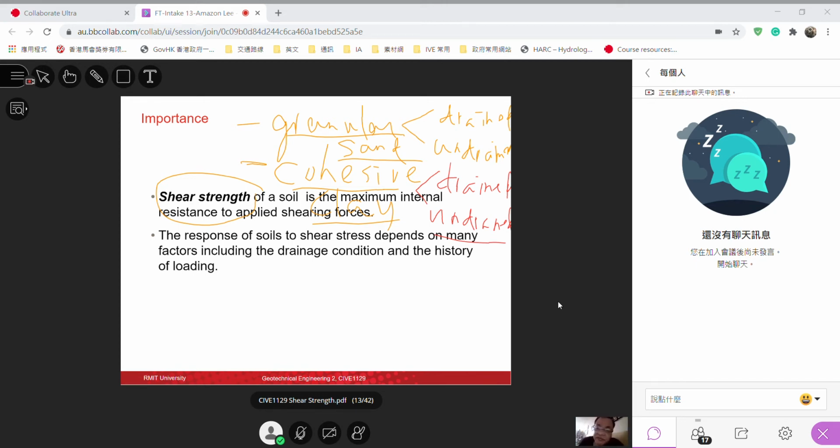Now, as I mentioned before, a lot of students are quite afraid of geotechnical engineering and soil mechanics, because in concrete, if you ask what is the strength of the concrete, oh, this is grade 30 concrete, then you know that the nominal strength will be 30 MPa. Oh, this is grade 50 concrete, then you know that our design nominal strength is 50 MPa. And we know that this structural steel is grade 500, then we immediately know the yield strength of the steel.